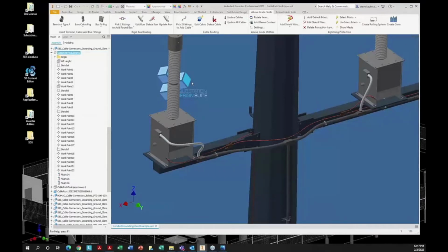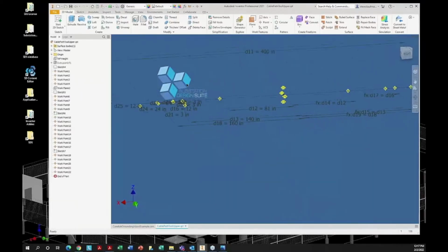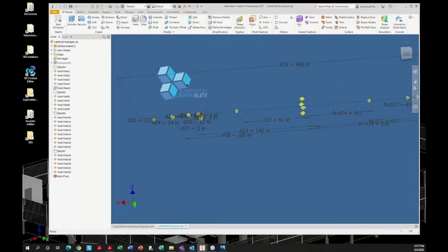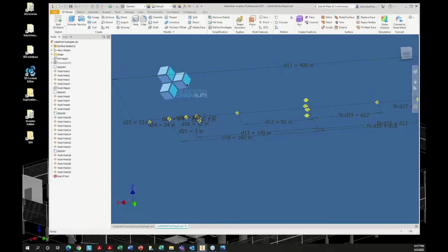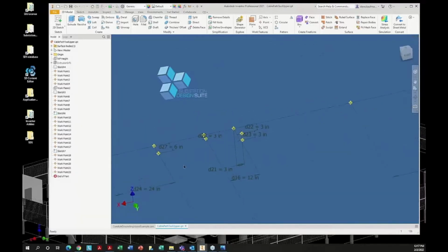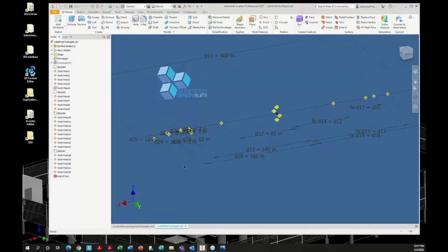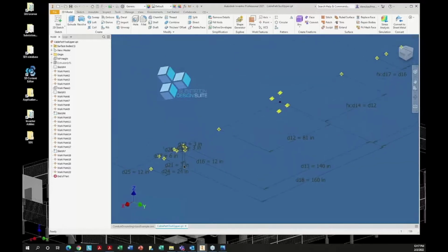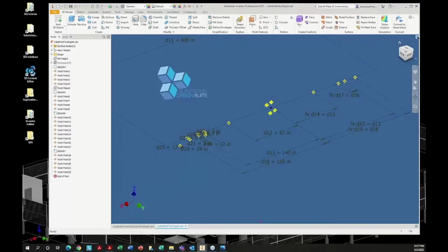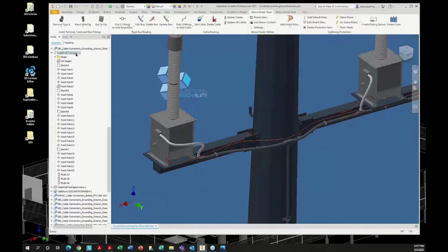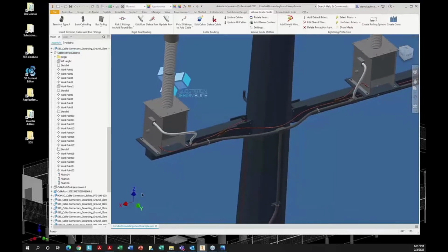What I did on this side, I created a part, and I placed the part in using ground and root. I create a part so I can take it out and edit it easily, and I'm in a quiet model. I'm not inside of my model by placing my sketch inside the assembly. And I did what I typically do, dimension everything. And in doing this, I got, wow, this is busy. This is a little bit too busy for me to work with. It's hard to make sense of it. I can also edit it inside of Inventor as well. I can edit while I'm in here as well. So that was the way I did it on that side.